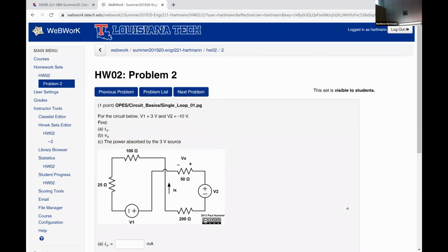This problem tends to mess with people a little bit. So what I would suggest you do is effectively untwist the circuit. Instead of having it in this weird twisted form, just draw it as a simple single loop circuit, one big rectangle.